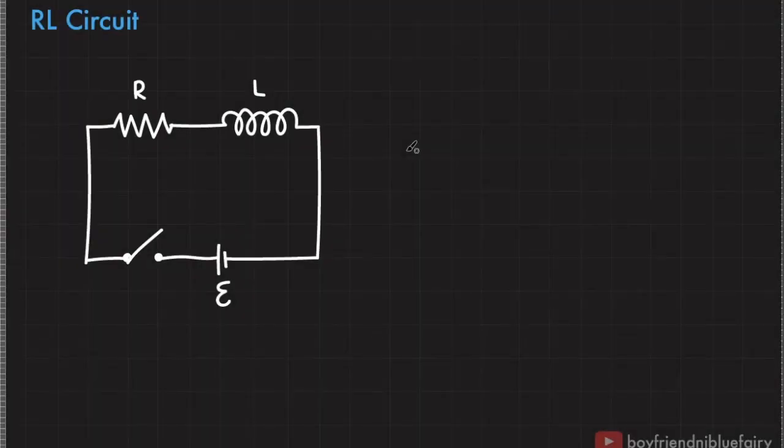Let's use Kirchhoff's loop rule for inductors to investigate the current behavior in circuits that contain inductors. Generally, we include inductors in circuits if we want to prevent rapid changes in current. Apparently, inductors are helpful if steady current is desired in systems with a fluctuating voltage source.